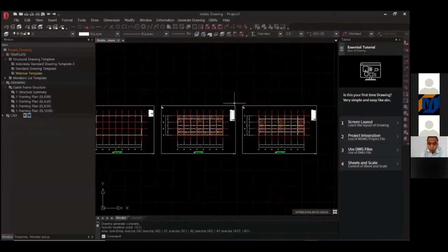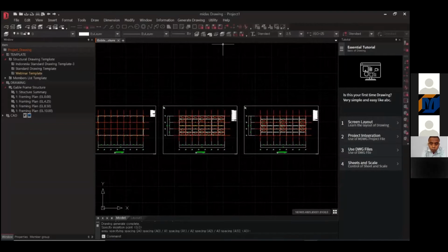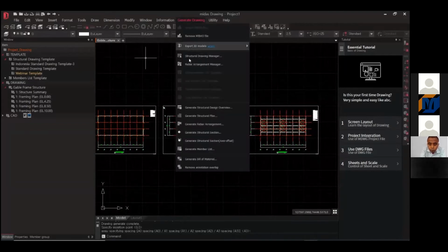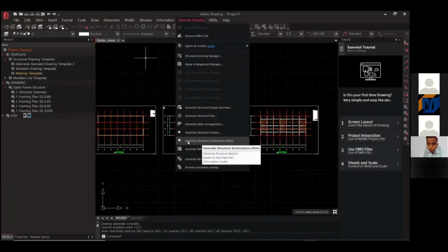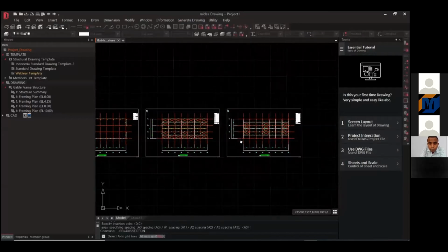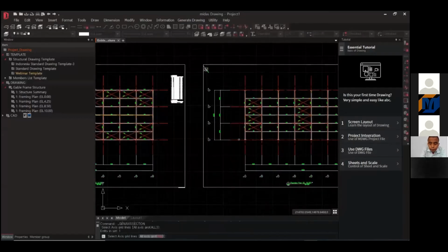In the last webinar, I mentioned that there are two main ways to generate the section drawing. In fact, since grids have already been created in the modeling, it is recommended to use the axis offset method. If you do not, create a cross-sectional view of the spatial position when generating the section drawing of the steel structure. First, select the red center grid line in column 1 on the floor plan. Then press the spacebar on the keyboard and set the visual range with the mouse.